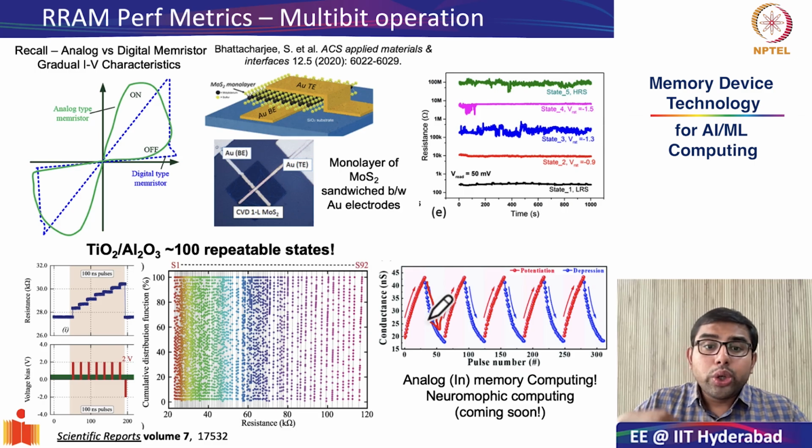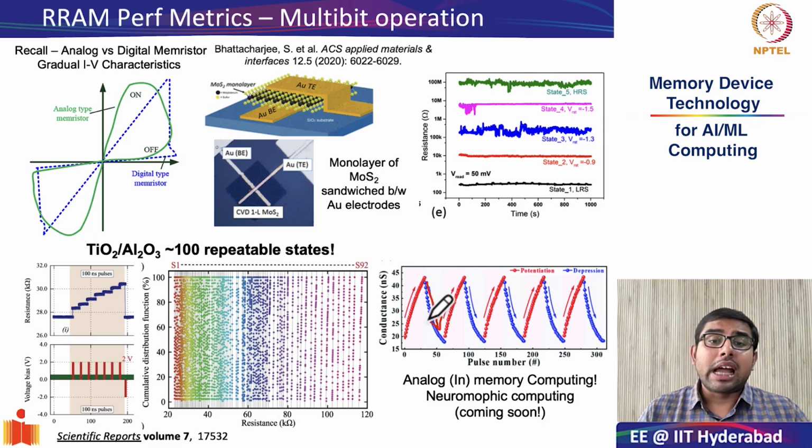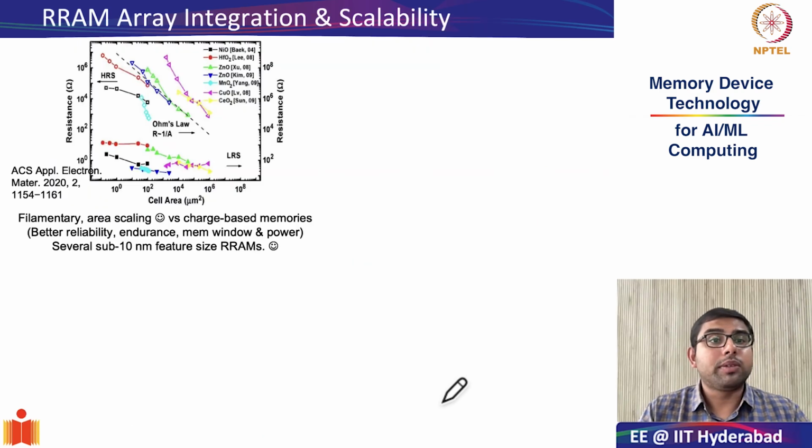Not only that, you can have access to these multiple states repeatably and cyclically. And this is what makes RRAMs very interesting for analog in-memory computing and also for neuromorphic computing, something that we will study in detail at the end of our course. Finally, we will discuss the array level integration and scalability challenges in RRAMs, followed by some commercialization efforts.